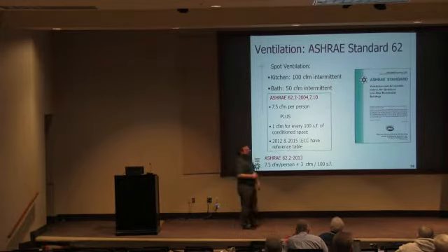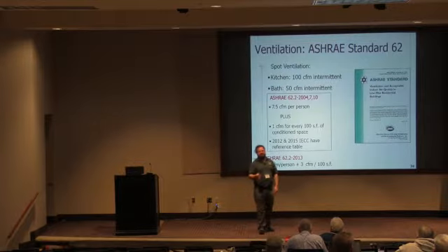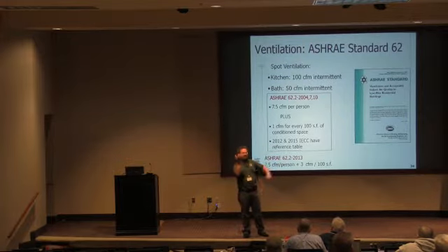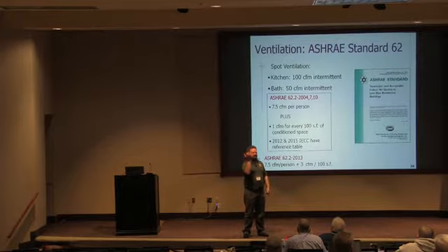And bath fans, seriously, how many of y'all have been out to a new home and seen a bath fan that's already installed in a way that the first thing it has to do is make a 90-degree or 180-degree turn with that exhaust duct, right? You think that thing actually pulls its rated CFM? Heck no. So, we always say if you want to get 50 CFM from a bath fan, put in at least an 80 CFM bath fan and install it, and then it might be in the 50 CFM range.